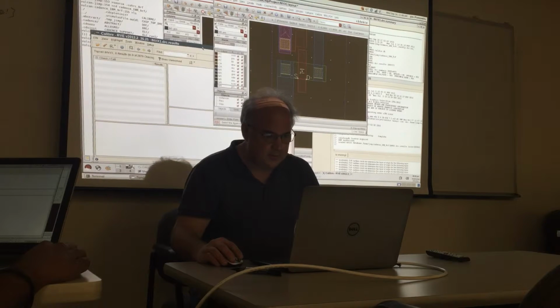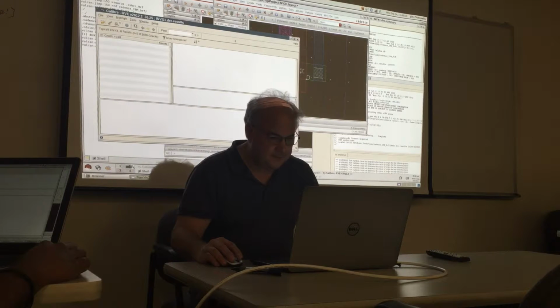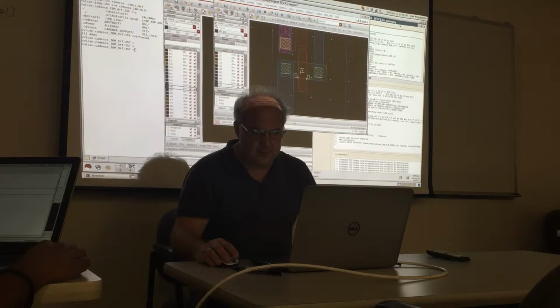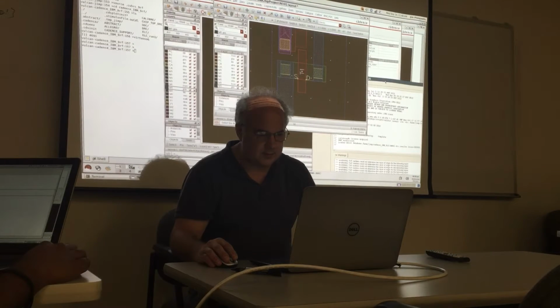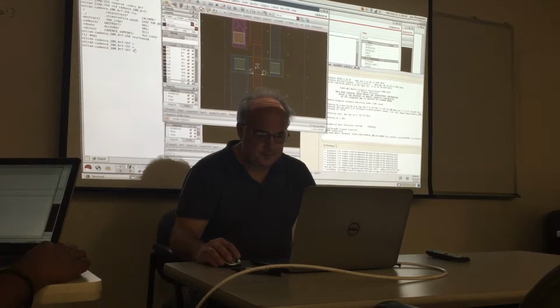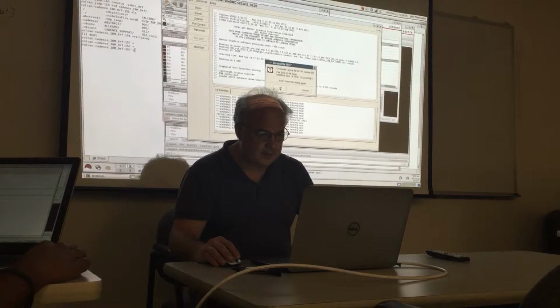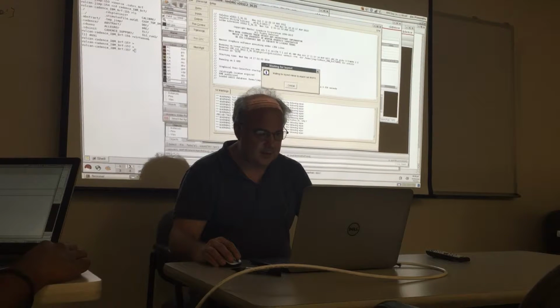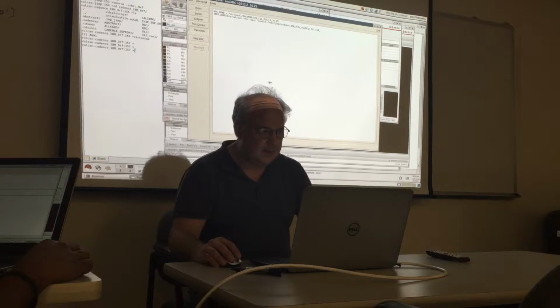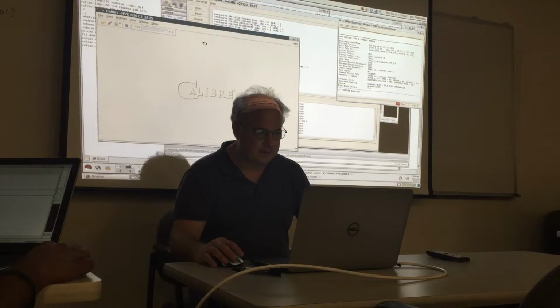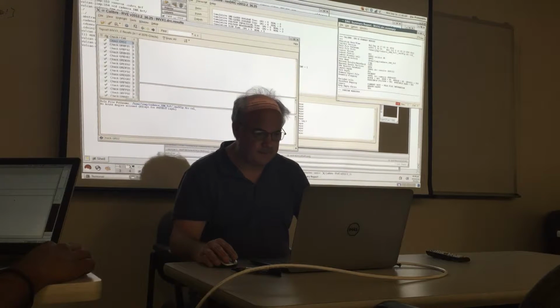Okay, so it's going to want to save this, and that's okay. I don't mind. For whatever reason, it doesn't like to do DRC checks unless you save. Then it opens up 3 windows, and of course the other 2 aren't useful. So you have to restart it? No, you can directly run it. Can you? Yeah. It asks to save. Oh yeah, it forces you to save it. Yeah, it's been modified. What did you do to rerun it? You just hit start DRC again. Okay. And it'll recognize that something's been changed. It's like a mini make inside of this thing.